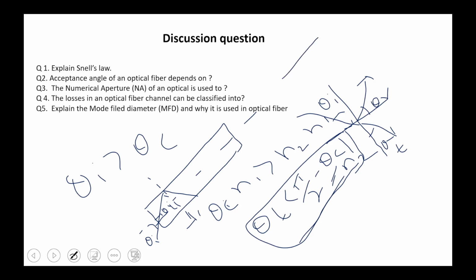These scattering losses are basically wavelength dependent. So the power loss occurs by scattering: that power will not travel through the core, and some power will go through the cladding. Am I correct or not? It means it is the scattering. Some power does not go through the core, so it will lose some power and be scattered in the cladding, not travel through the core.